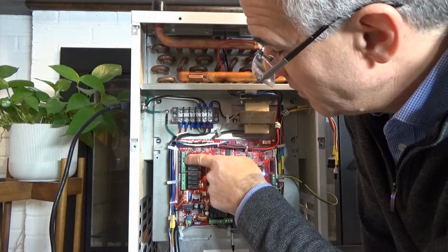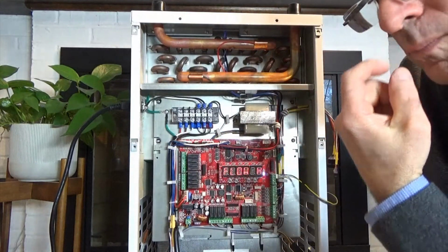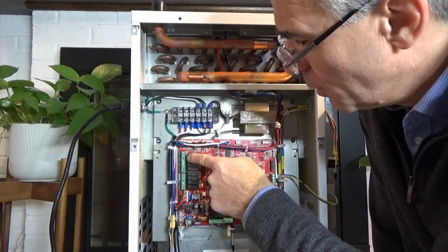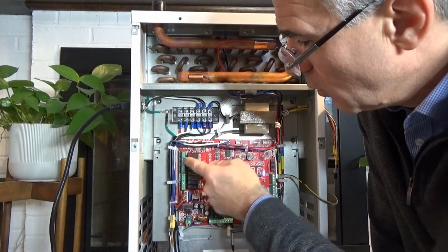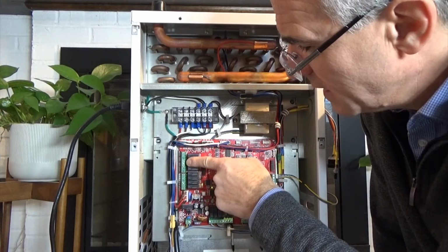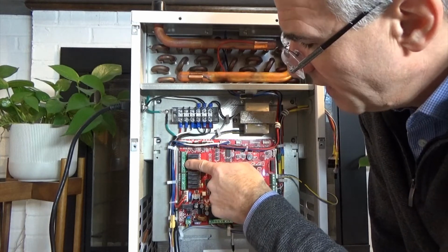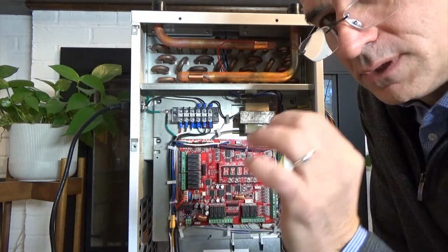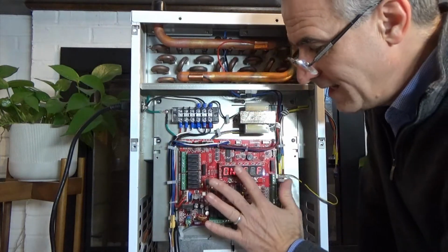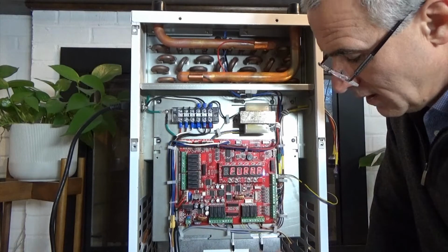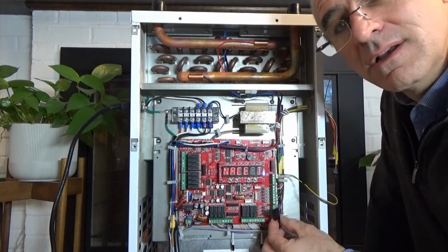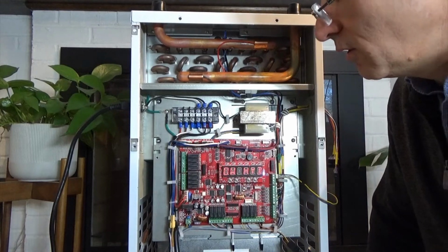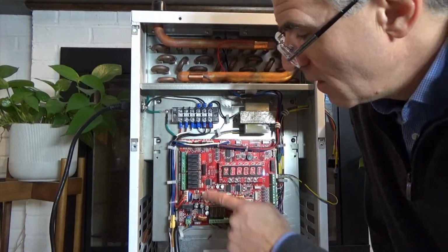Then we have dehumidifier, which we're not using yet. That'll be for a future component that we're going to be incorporating into the iFLOW package. We have the humidifier contact. So that is going to supply 24 volt output to your humidifier on a heating call when your humidity sensor sees a humidity lower than the set point that you have programmed into the board.